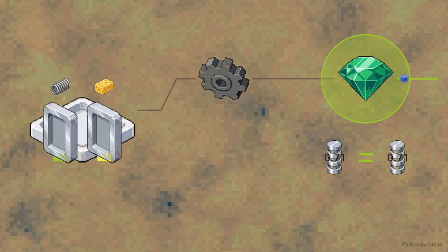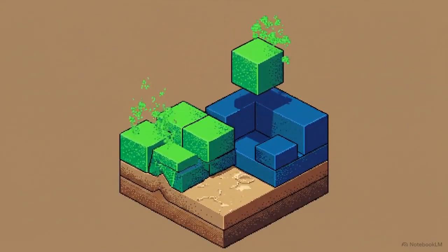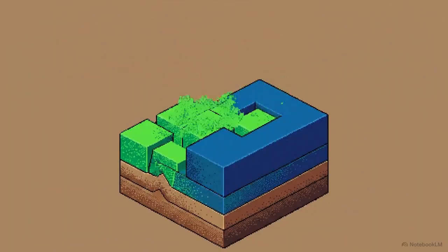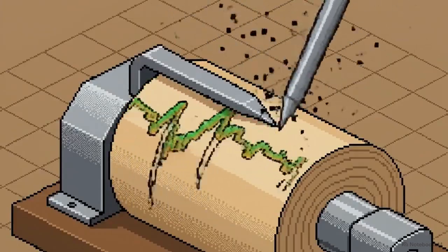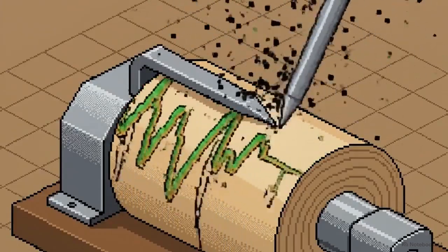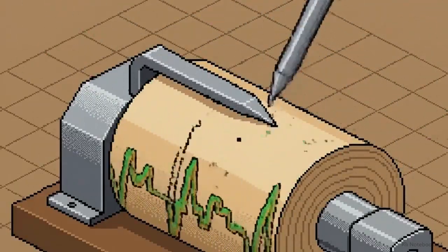This is the moment the loop breaks because the input properties and the resulting strain are finally in perfect mathematical agreement. Through this iterative process, a rigid computer program can systematically narrow down and identify a state of equilibrium within a chaotic, nonlinear system. It is important to note that the final output doesn't actually track the soil's second-by-second behavior as the earthquake progresses.